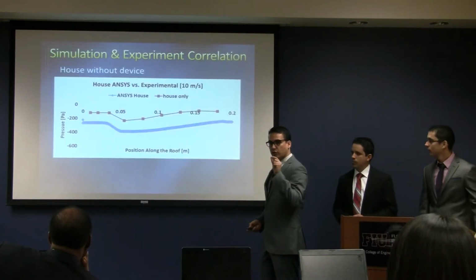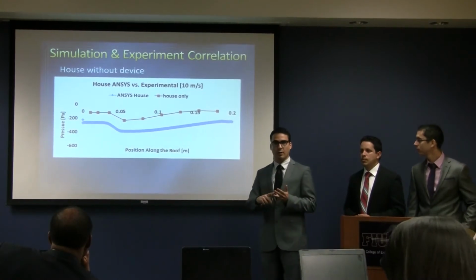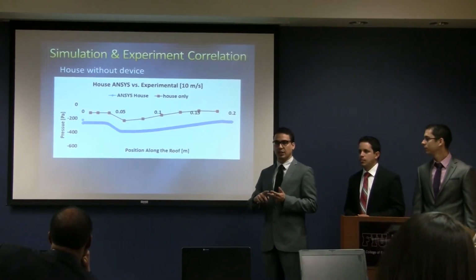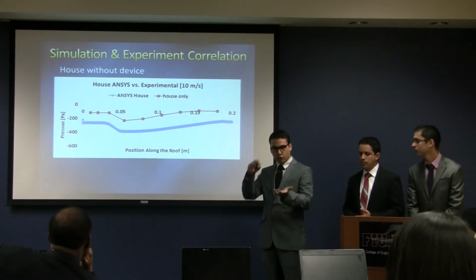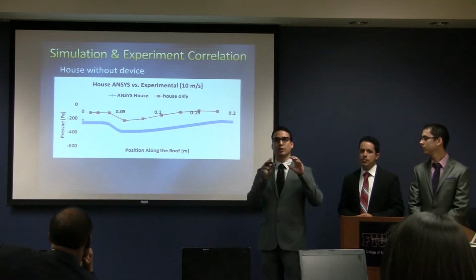Now, it's important to mention that all the values of the boundary layer conditions, I'm talking about the velocity inlet, all the dimensions from the cross section, and the RPM of the turbine that we measured, were put into ANSYS.